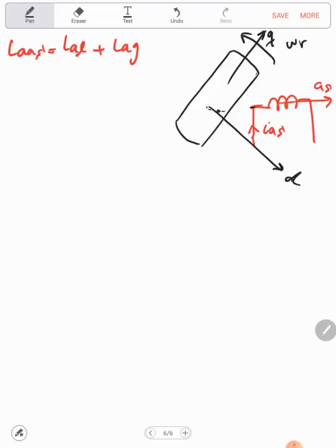So now injecting current in phase A will induce magnetomotive force. So the first thing, the MMF will be generated in phase A. So the MMF along AS, according to the Ampere law, will equal to NS IAS.